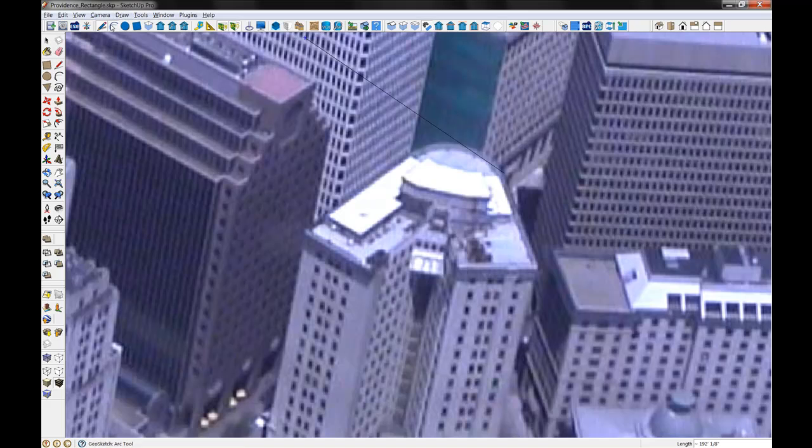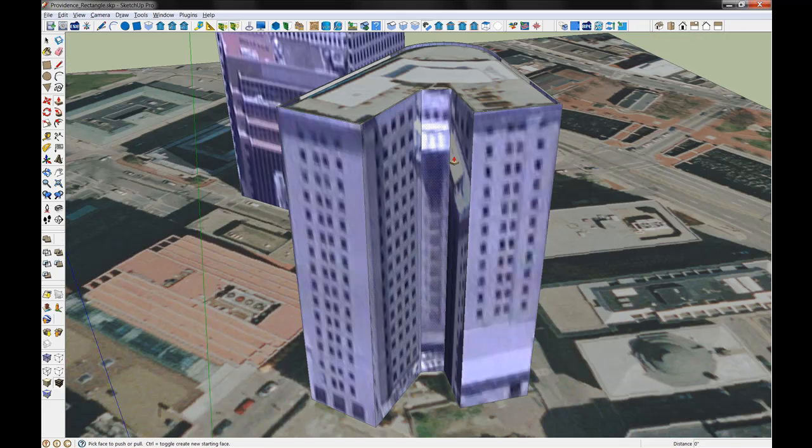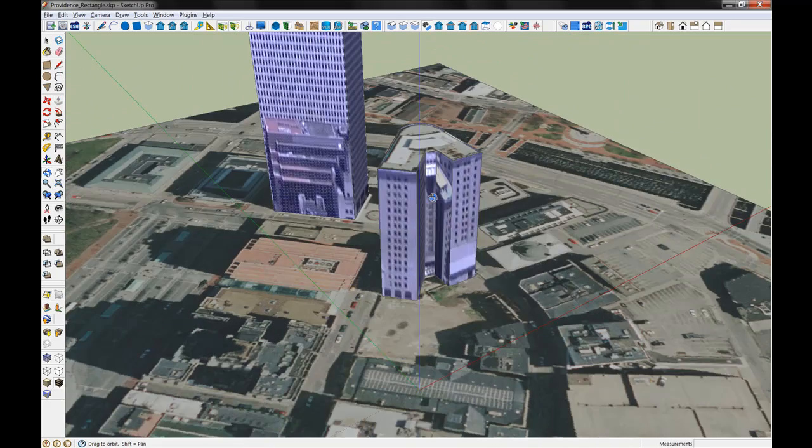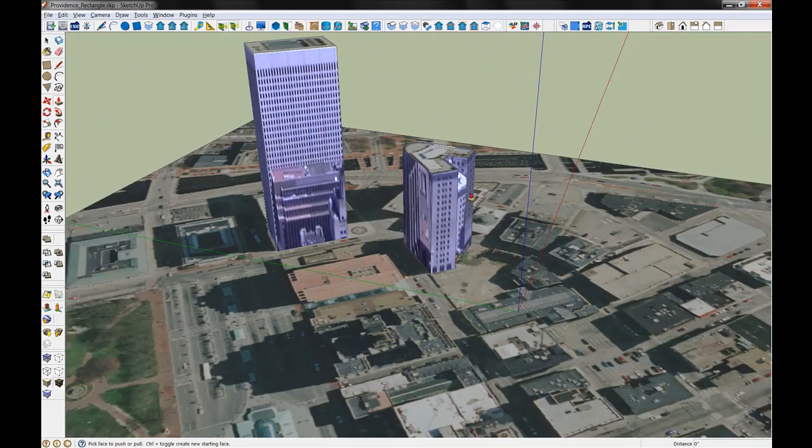And then we'll switch to the arc tool and close the end of the arc, and our inferencing also tells us when that arc is tangent to the adjacent edge, and then it will be extruded down to the ground with a parapet roof. One problem that we see is that some of the faces are obscured by other buildings. There's a tool called the TextureFace tool to correct that.